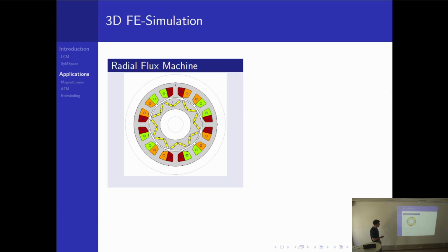In the rotor you have the magnets with a certain magnetization direction, and this goes into the variational formulation on the right hand side. In the stator you have the winding; these colored slots depict the winding scheme of this electrical machine, and this is also a source on the right hand side of your PDE. The gray material is nonlinear material, electrical steel.